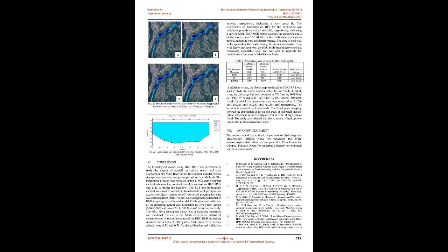Cross-sections representing the maximum water level during the 4 return periods along the lower reach of Modi River Basin are shown in Fig 22. The results from the flood analysis show that the area covered with forest is more vulnerable to flood, as demonstrated in Fig 21, A, B, C, D. With an increase in the flow value, the inundation in the forest area seems to increase.